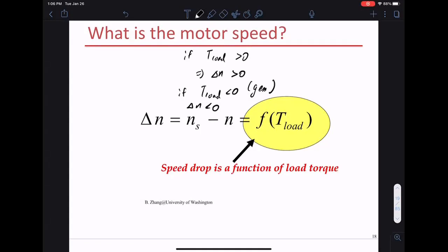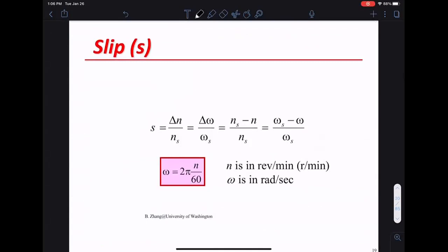So this is the synchronous speed. If you look at the equations, if you recall from 351 or an equivalent class, we talk about slip. Slip is a normalized measure of the relative speed difference to the synchronous speed. That's just more convenient for using equations, to think of the speed difference as a fraction of the synchronous speed. So what is the normal range of slip? Anybody remember the magnitude that slip can take?